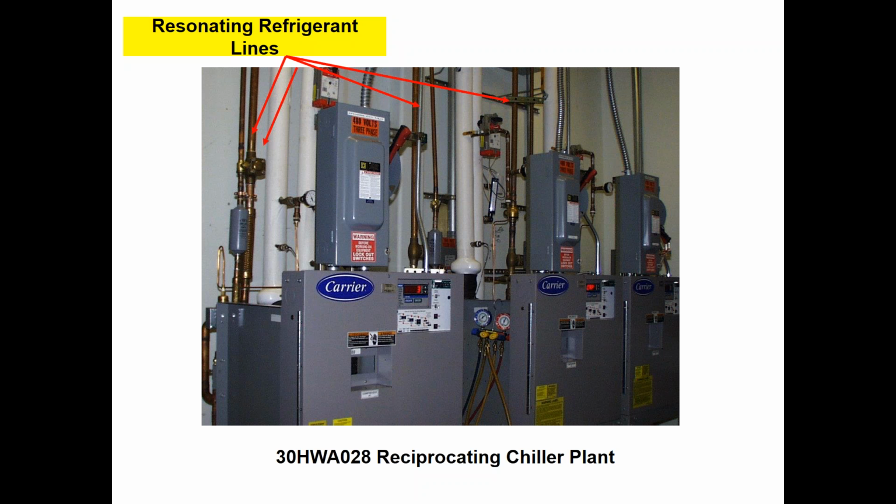You're going to have some vibration out of all pipe with refrigerant, and attenuation of compressor noise. So be careful of the structure that you're mounting it to, the walls, just like residential. You need to watch your penetration through the side of the house. You want to watch where you strap the pipe to so it doesn't attenuate into the walls or the ductwork. And commercial is the same thing.